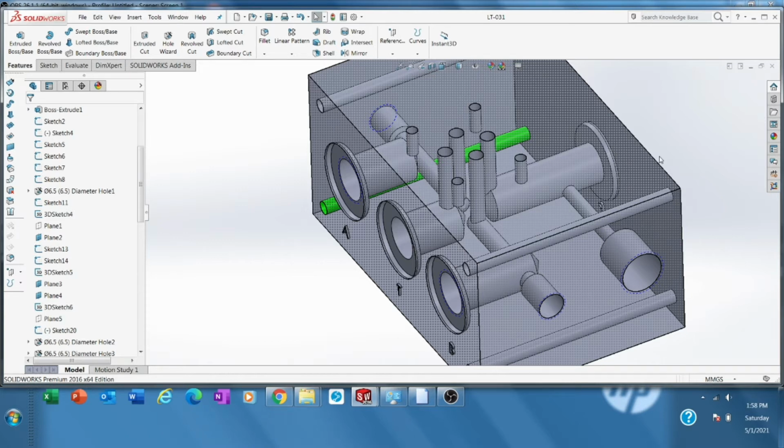Actually, companies like Yuken or other hydraulic companies also provide manifolds, from the simple manifold until the complex manifold. You just check their catalog. So I believe they will make it cheaper, because they make it in big lots for all their customers. But the weakness is you have to design things to fit that dimension. You cannot modify the length and the height, etc. So there is a pro and con for that. But to save cost, you can consider their manifold.